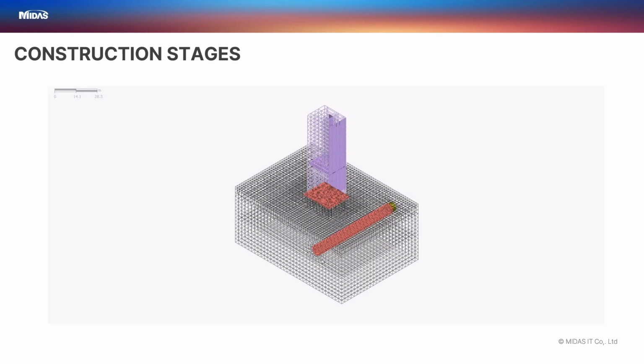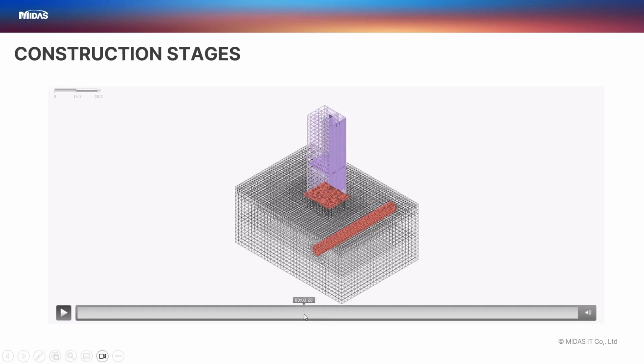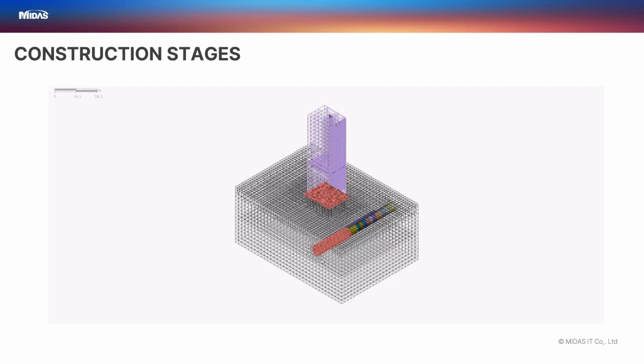One thing to notice here is that the jet grouting is activated just before the tunneling reaches quite close to the building vicinity, because that is something we are not willing to take the risk of.